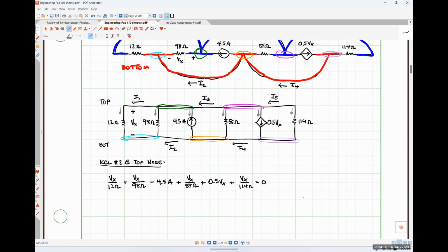That is the most powerful and important piece of information for a circuit where everything is connected in parallel because it's common to everything. So once we have Vx, we're in really, really good shape. I'm not going to bother actually solving for Vx, but we can see here that we have one equation with one unknown. So we should be able to solve for that voltage Vx very easily. So under the assumption that we use this relationship to solve for Vx, now let's figure out how to determine all of those currents, I1 through I5, that you're actually asked about in the homework problem, right?